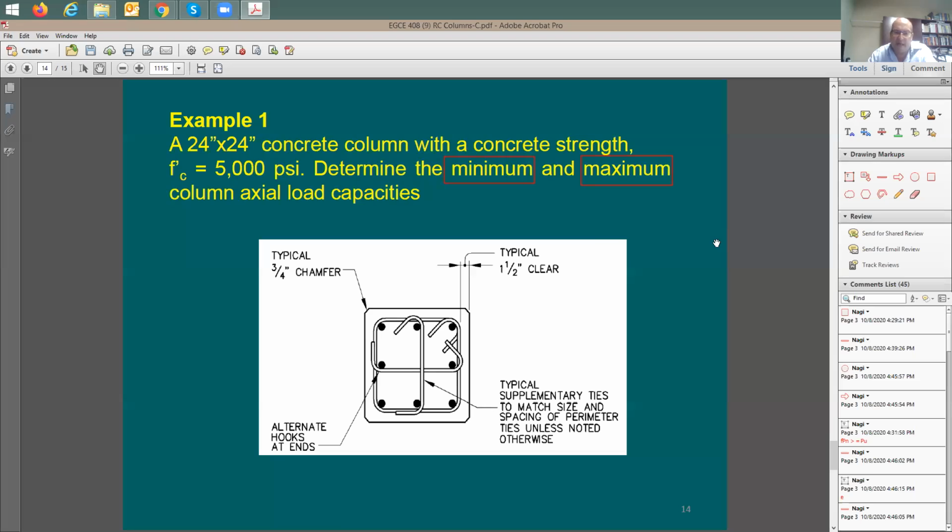Let me look here at the column demand I just calculated out in my analysis. I'm going to be doing structure analysis, figuring out the column axial load, and then say, yeah, all the column loads that I am looking at in this project, it's maybe about 1,300 kips, 1,400 kips, 1,500 kips. You see, this is good. It means this column is good to support these loads. And what I need to do now is to work on the amount of reinforcement for each column type.